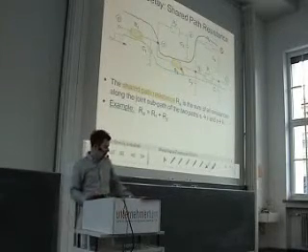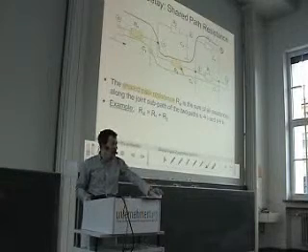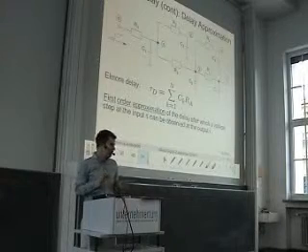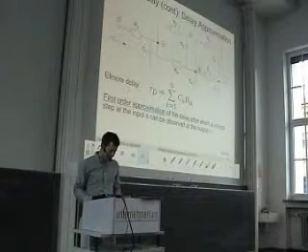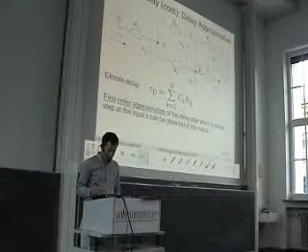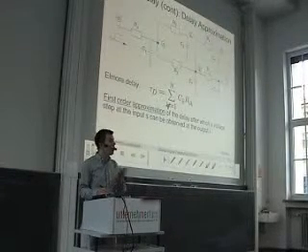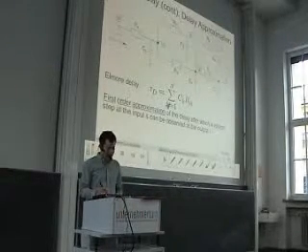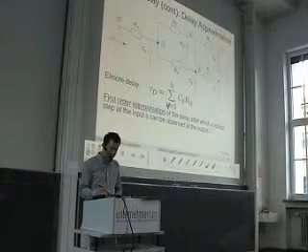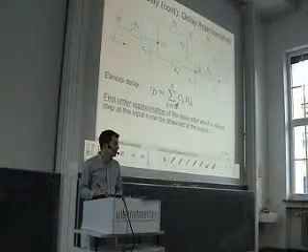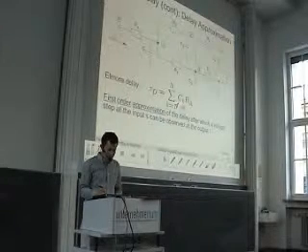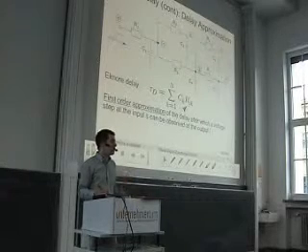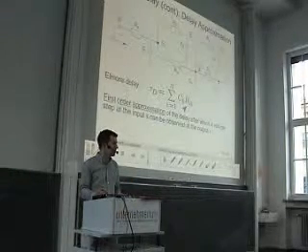Using these definitions, we can define the Elmore delay. The formula for the Elmore delay looks a little bit complicated at first view, but actually it is not. We build a sum over all nodes. For each node, we calculate a time constant given by the node capacitance and the joint path resistance from this node to the input. You might ask, joint path resistance requires a second path.